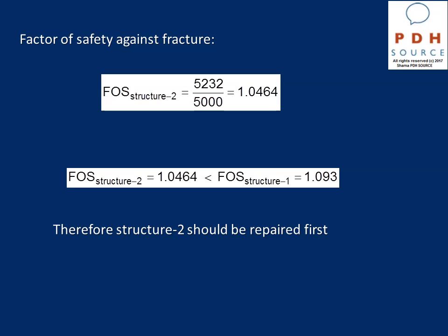The numbers show me that although it is a surface flaw, the factor of safety here is less than the other one, so structure 2 should be repaired first.